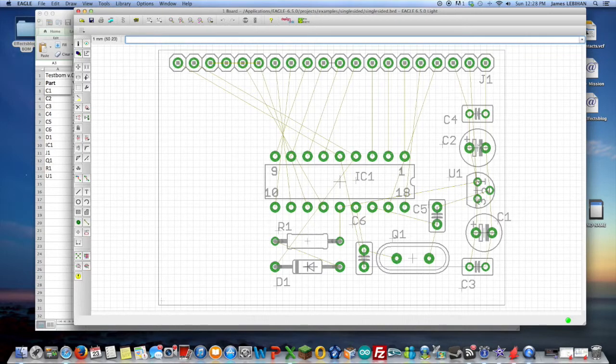So here's C1 and C2, and I have a 1mm pitch for these squares. So I've already measured this, and I happen to know that a 4 or 5mm diameter cap will fit in here okay. And then I also have a lead spacing of about 2.5mm. It's 2.5mm lead spacing on these. So if I really wanted to match these parts up correctly, I would get an exact 2.5mm lead separation. Sometimes we may find that they're smaller than that, and in this case, through hole electrolytic caps, I can spread the leads out a little bit, so I have a little tolerance there.